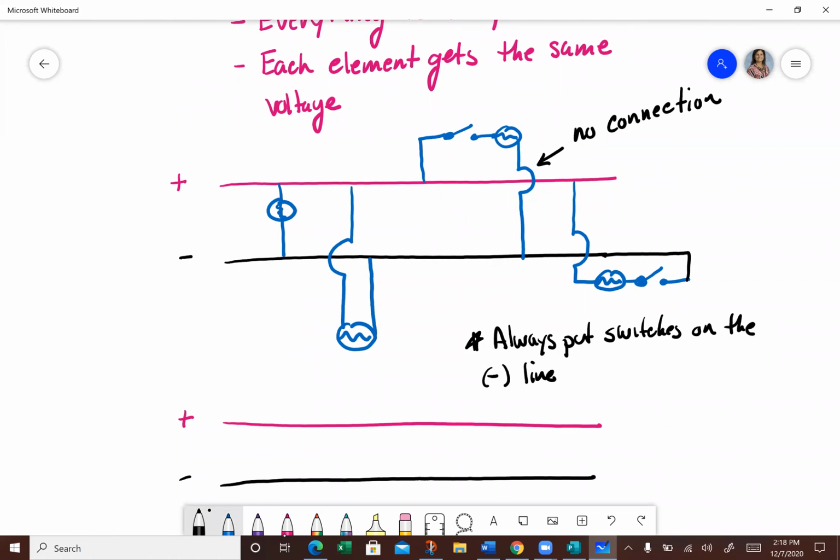That be negative, with one light being here. The next light is there. This light, I left the positive, went to a switch, left the switch, went to the light, left to negative. This one over here, I did my light first, then left and went to the switch. So these two pictures are the same.